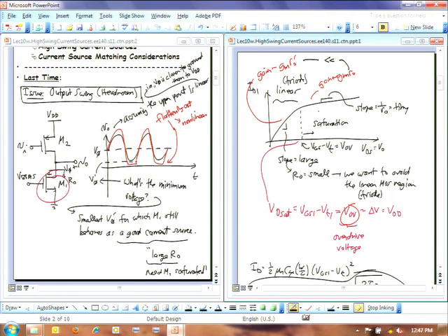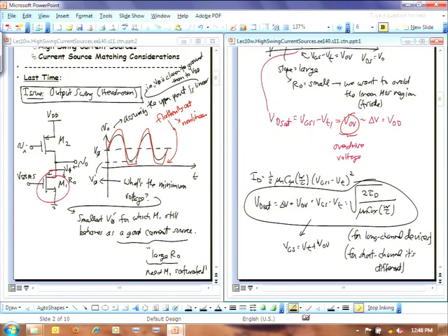Okay? And I pretty much define this overdrive voltage here, which is just VGS minus VT. So that's how much higher your gate to source voltage is than the threshold voltage, and so no wonder we call it the overdrive voltage, because to turn on the transistor you only need to get VGS equal to VT, the threshold voltage, but here usually we're raising it versus VT.